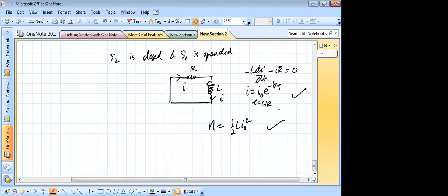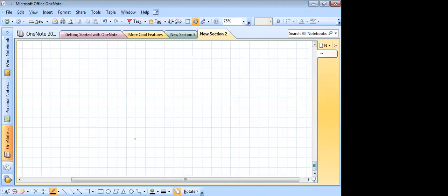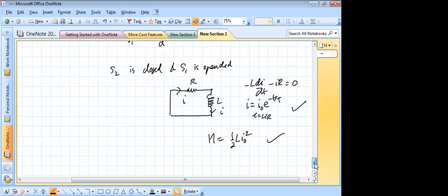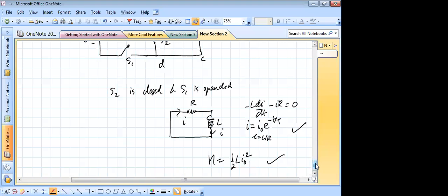Okay, let's look at this one. 20-second, right? This long straight wire one. Sir, I have a doubt in this. Yes, tell me. The I square R part, the A part I got, and for the B part I would not have to integrate it. Yes, you can integrate, but ultimately, logically also, the energy stored in it will be dissipated as heat. So directly, integrate I square R dt from t equal to 0 to t tending to infinity, you will get that only.